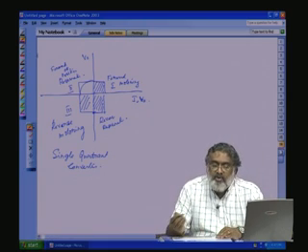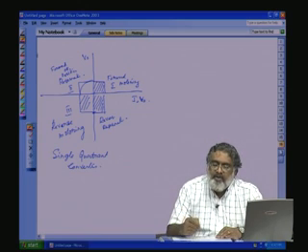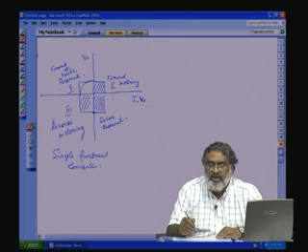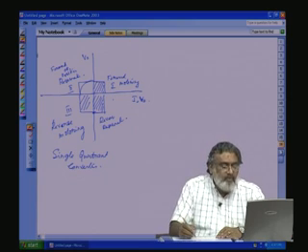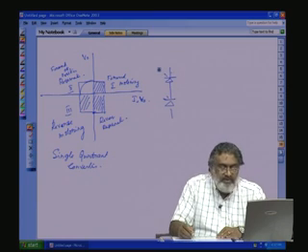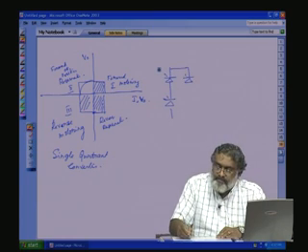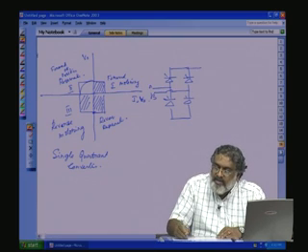The previous converters are all called semi-controlled converters. Even though we are using 4 devices, only 2 switches are used for controlling the output voltage, so it is called a semi-controlled converter. Let us talk about the fully controlled converter. It will be like this. We remove all the diodes and put thyristors, so we require 4 thyristors to be controlled, and the load will be like here.